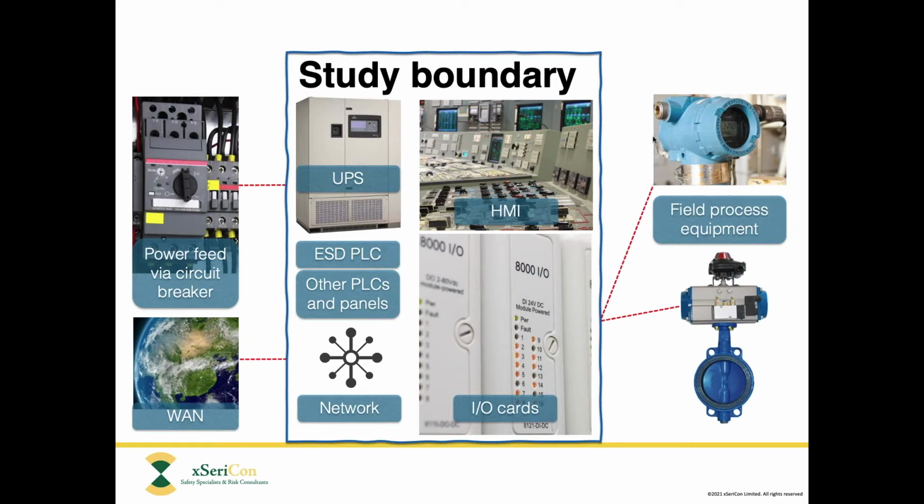It's based on a detailed checklist that mainly contains what-if questions, but also contains some yes-no questions as well. And that detailed checklist, if you want to get hold of it, then please contact us and we can discuss. We'll certainly be happy to send you a sample on request. And the purpose of the CHAZOP study is to identify any issue in terms of deviation from normal operation or normal behavior in the control system that could ultimately cause a process upset with significant consequences.